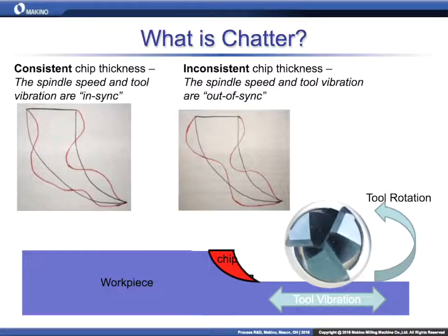When you follow it from the beginning of the cut to the end of the cut, it still follows the same pattern that you would with the idealized or the nominal chip. So at the beginning, from the previously cut surface, the thickness as you follow that wavy chip down is at least consistently wavy, if we can say that. Yeah, the cross section is following that thick to thin pattern, so you're getting this predictable, smooth transition in the cutting forces. Yes.